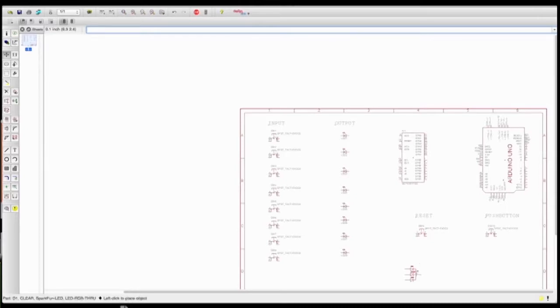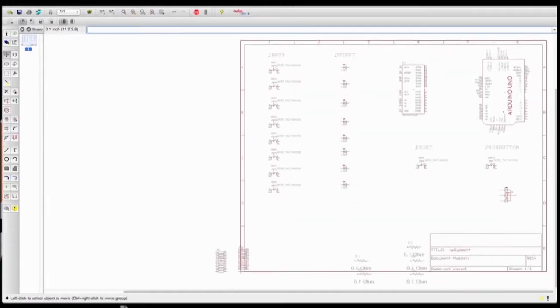And then I have my LED right here, my 3 color LED, the RGB, and it's going to have some resistors. So I'm just going to line them up here as well, and we'll clean this stuff up later. I'm just trying to place everything right now. And then these are going to be for the I2C. And then we have our 2 resistor arrays. And each of these input and output have a resistor array. I'm going to put them right here, just like that. And I think we're pretty much laid out. So now we can get started creating the actual connections.